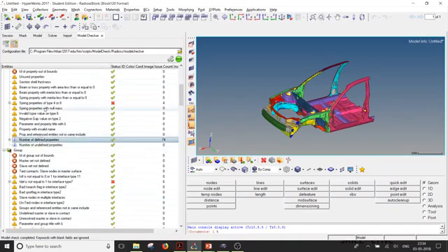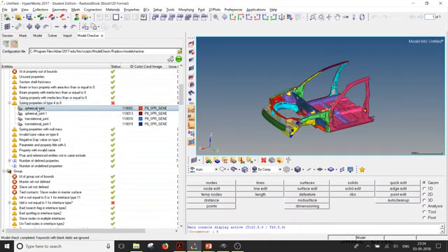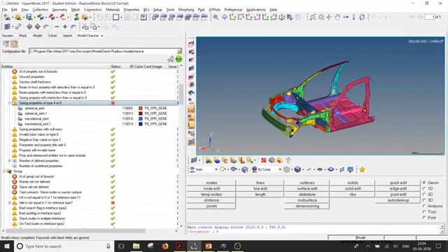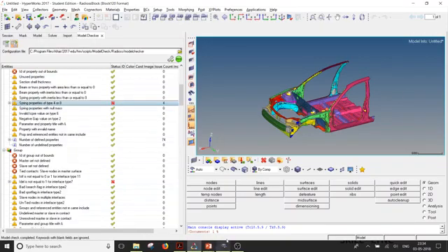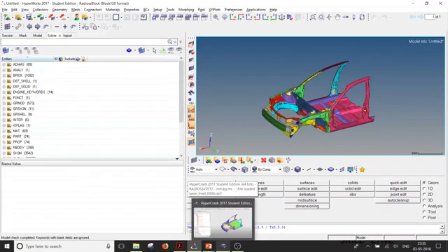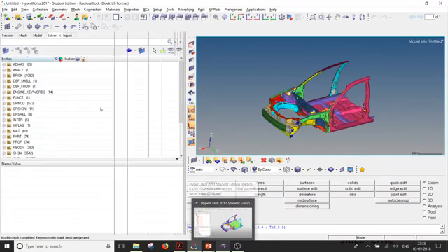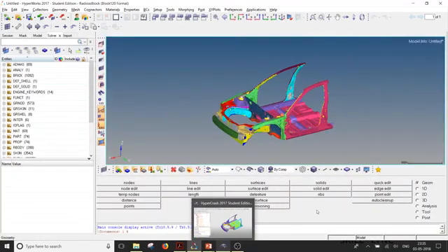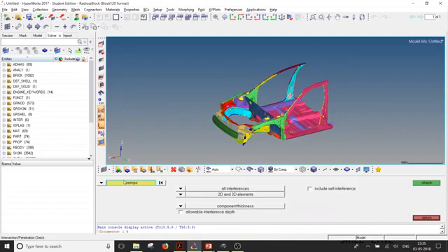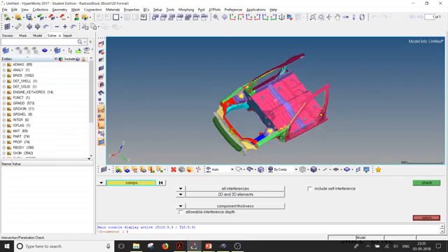You can take a look at those. And then you can apply corrections. I would highly recommend using the HyperCrash model checker though. Well, anyway, for penetration checks in tools, you have a penetration checker, and that can do the trick for you. As of now, I think there are not many penetrations in this model.